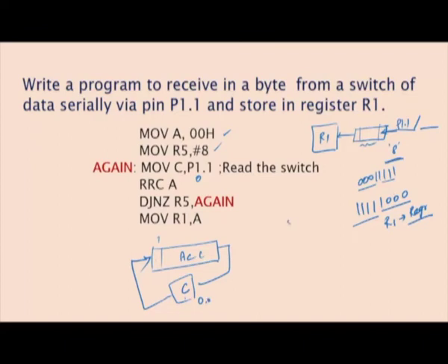Automatically, initially all values in the accumulator are 0, right. Now, I am inserting the 0. So, 3 zeros are inserted, I will consider the same. After that, when the value is 4, it means I have pressed 4 times. Now, consider the number as 1010, alternate on and off, right. Now, I have pressed the switch, so the switch is closed. Switch closed means carry is 1. Carry is 1 means the carry is inserted in the MSB. Now, the remaining bit positions are shifted right. Okay. Now, the counter value is reduced to 7, so again I am repeating the process.